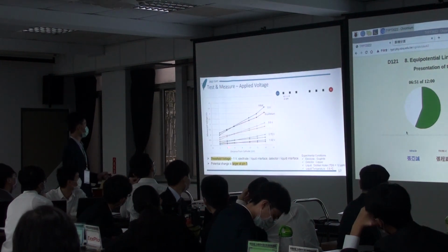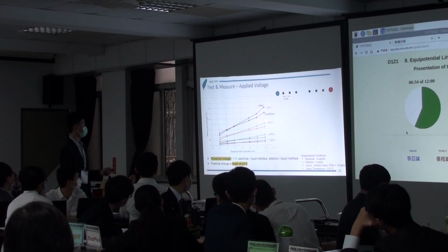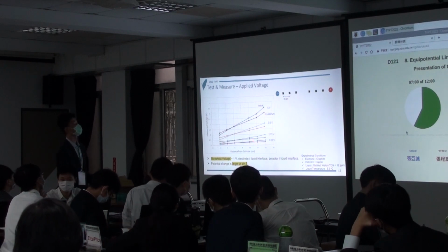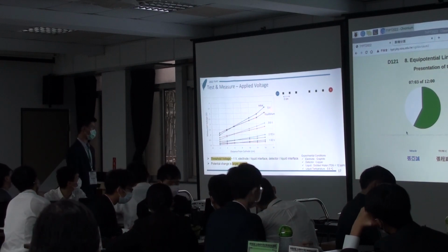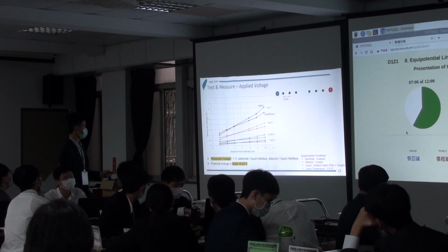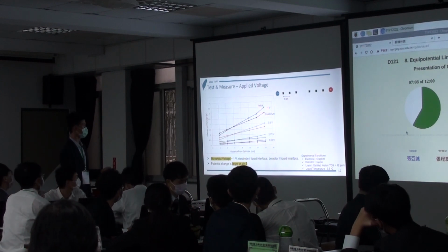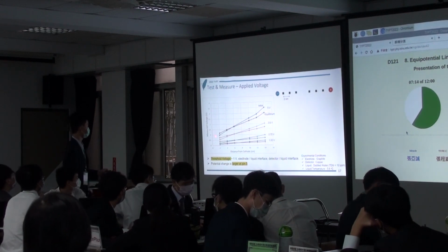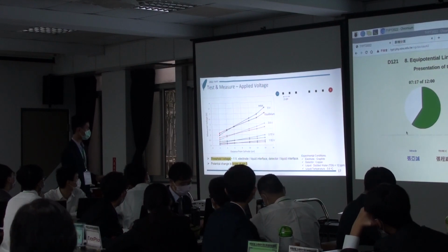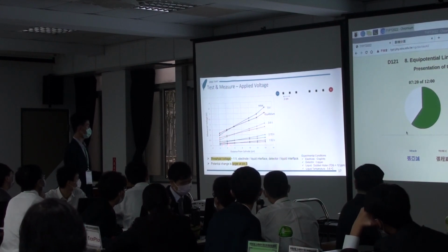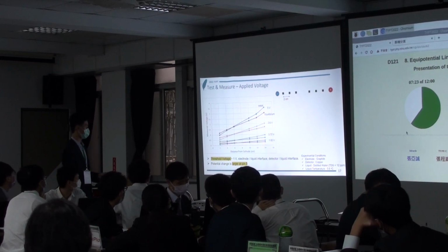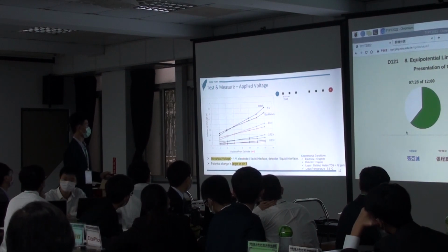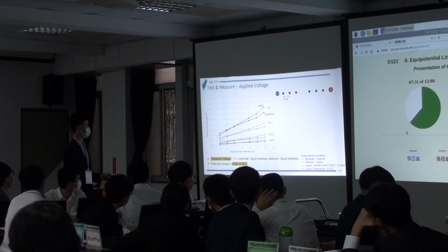So this is a graph showing how the voltage changes with respect to the distance from the cathode. And you can see that for higher voltages, the slope is larger, and the potential change at N5, which is the pin closer to the higher potential electrode, is larger than the potential change for pin 0. And you can see that when the supply voltage is lower, the lines become flatter and flatter, and that is because the EDL shields some of the voltage we supply. So from here you can see that there exists a threshold voltage, and that is about 1 volt.